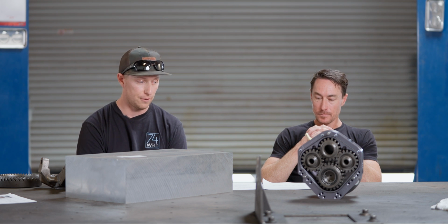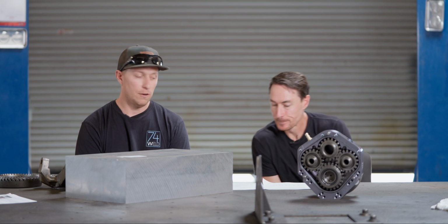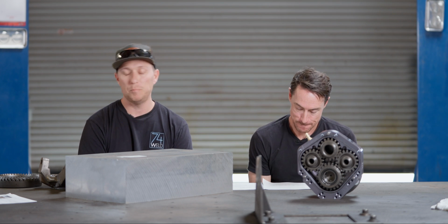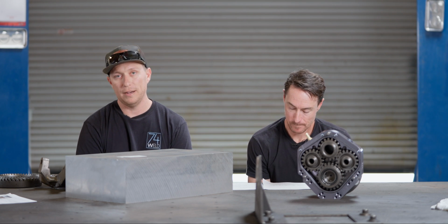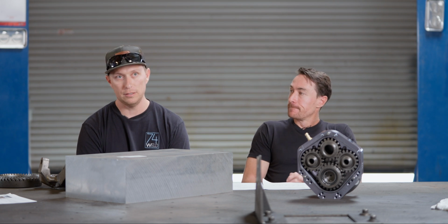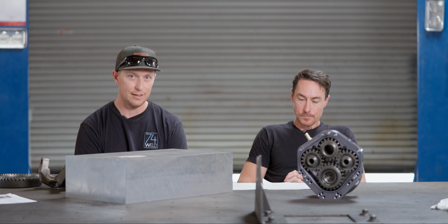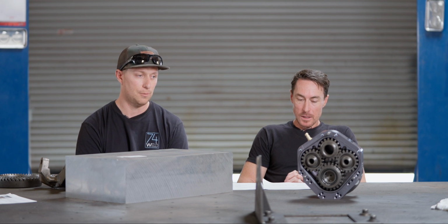So you're shooting to be under that. Yep. So you gain, what, like 12% strength or something like that. But your density is going to go up by like 2.4 times. So the strength to weight doesn't really balance out there. There's not much you can do about adding that additional weight to the part.